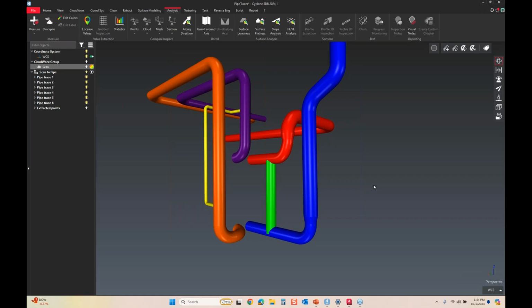Do you scale the point cloud model? You know, that's a great question, actually, because a lot of people ask that question. So thank you for asking that. You never scale a point cloud model. It is always one-to-one. Now, with that being said, through the software I have up on the screen, if you had to, you could.